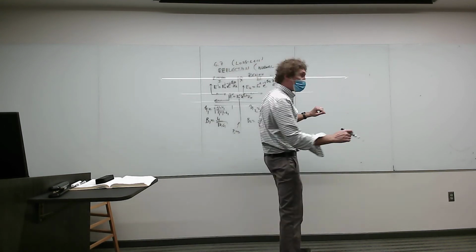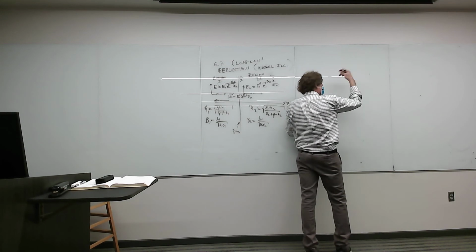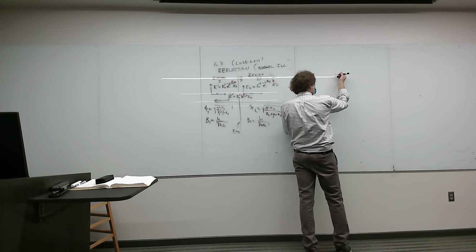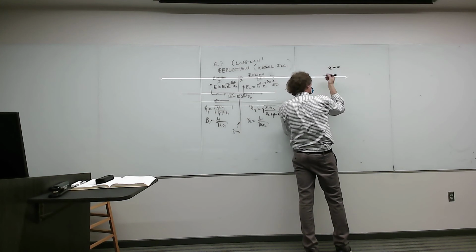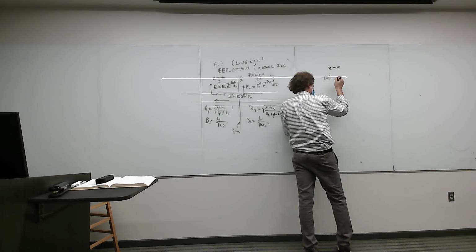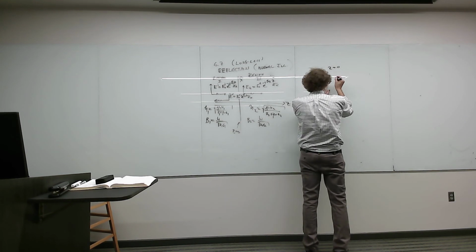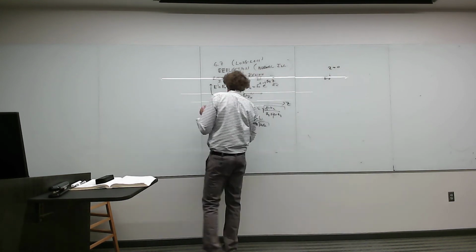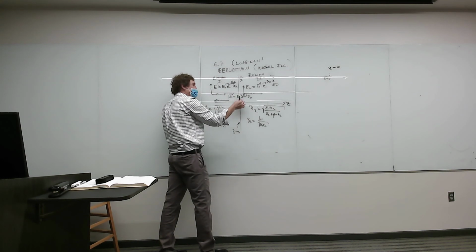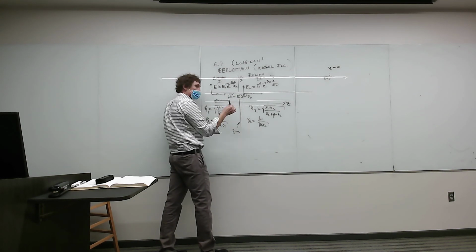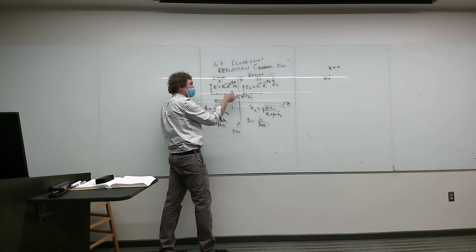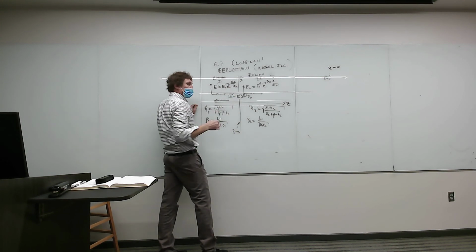Now, follow me. The electric field at the interface, z equals 0, on region 1 would be E naught incident, right? And then it would be plus E naught reflected. You see how if I'm right at the interface and I'm matching the field components, saying the electric field tangent on one side is the tangent electric field on the other, that z is 0, so these e to the j terms go to 1.